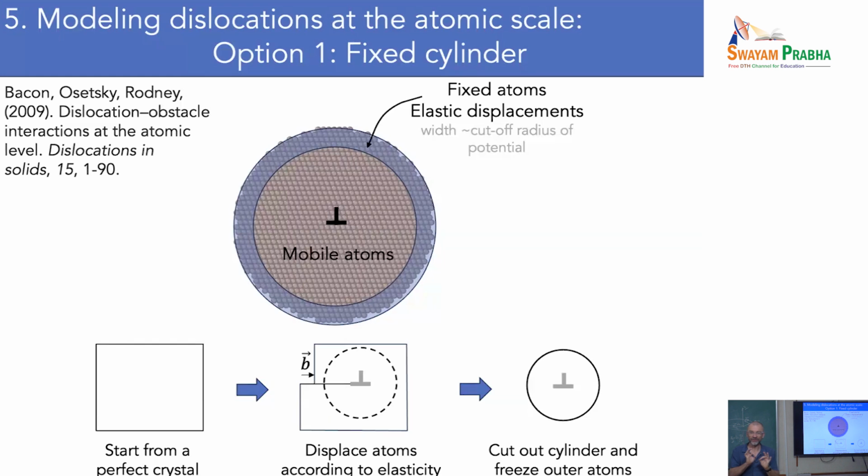But since they cannot, that will create a repulsive force on the dislocation. So actually, if I have free surfaces, the dislocation is attracted by all the different sides because it will disappear. If it's fixed boundary conditions, then it is repelled by all the sides, and so it's going to stay in the middle.